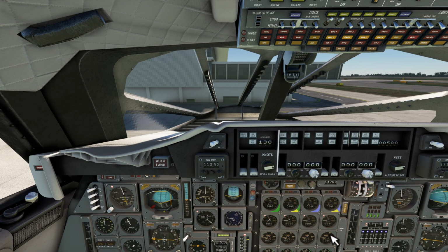In this view, we check our autopilot settings. We switch to INS, that means after we turn the autopilot on and go to INS mode, we're going to follow our very simple flight plan that we planned before. That also means that the right side is active and is going to be programmed automatically by the flight plan.